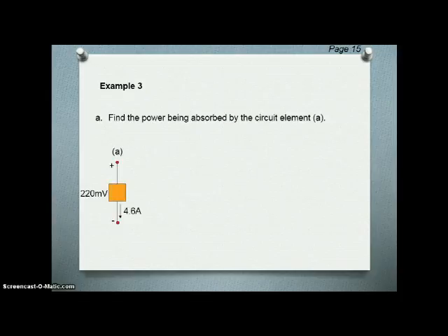Let's see how much you got. So here is another example. Calculate the power absorbed by the element. So check, how do we start? Look at the positive terminal, no information. Look at the negative terminal, yes, there is information about the current. Extend that. If the current is flowing outside, that means the current should originally start from here. So what is the current? Is it going out or going inside? The current is going inside the positive terminal. That means the element is actually absorbing.